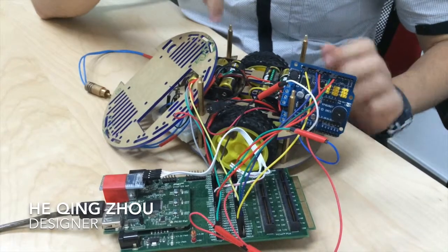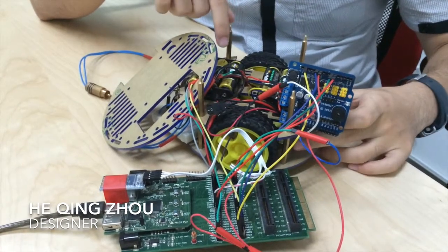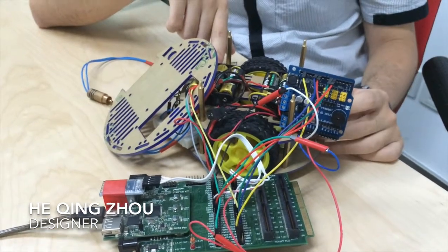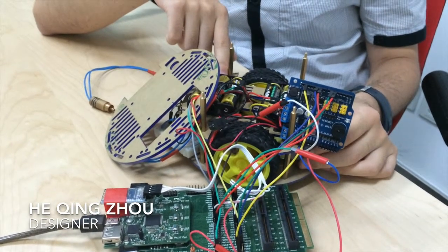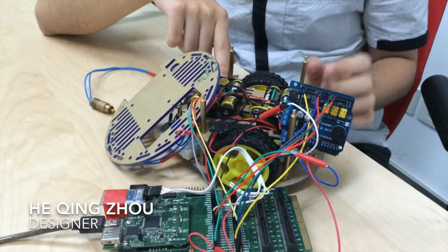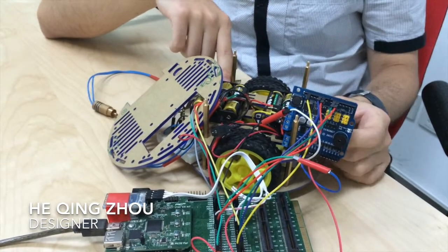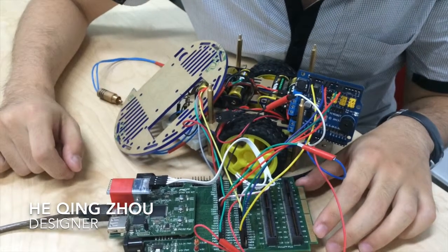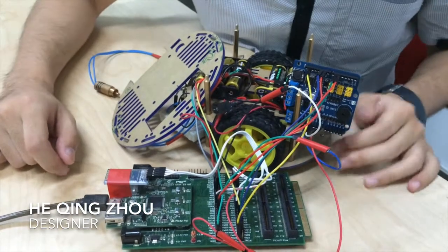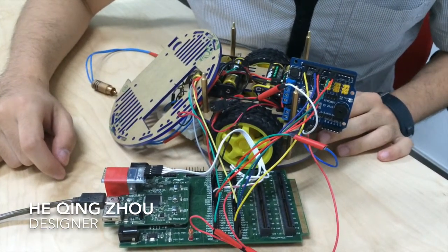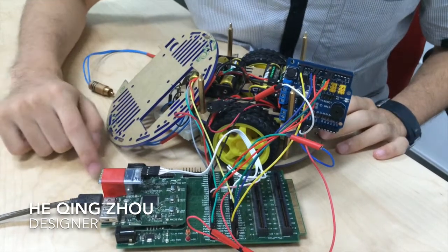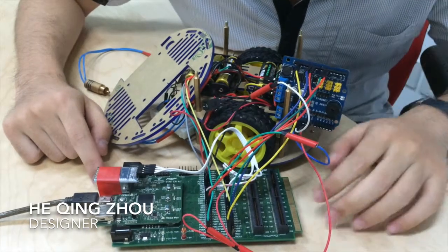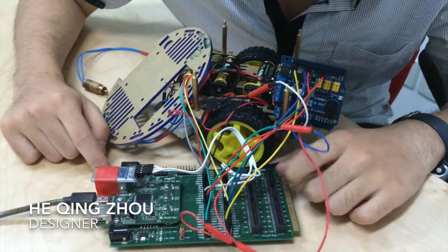And then when we have the two motors drive the wheels to rotate in the same direction, we can have this auto robot move forward and backward. And then when we have the motors rotate the two wheels in not the same direction, then the auto robot will either turn right or turn left. And since we intend to have this auto robot be controlled by a computer wirelessly, we have an outside Bluetooth module, and it interacts with the UART module of the PIC32.